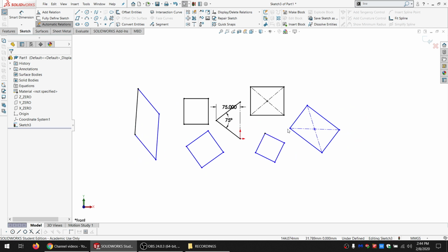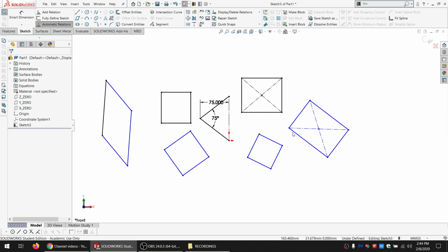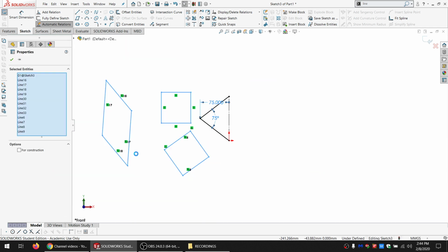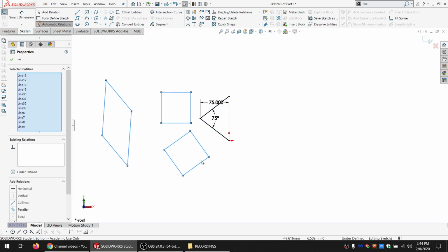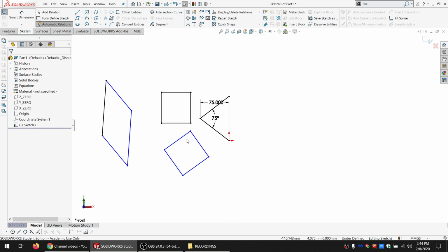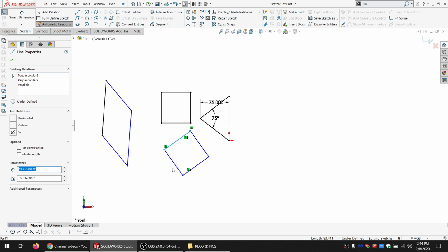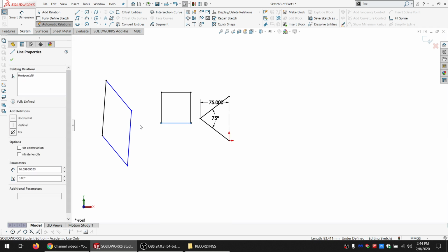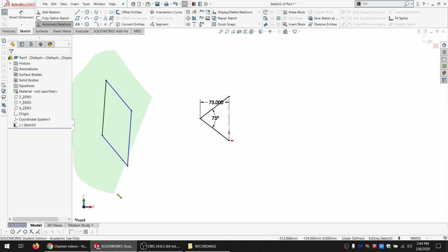And that's very useful for a lot of things, but many things also require curves. So I'm going to delete all but this original bit. Oh, I didn't mean to delete quite that much. Another thing is, if you want to select something, obviously you can just click it. If I want to select this whole rectangle, I can right-click it and click Select Chain. And then delete it. And I can also drag around it.